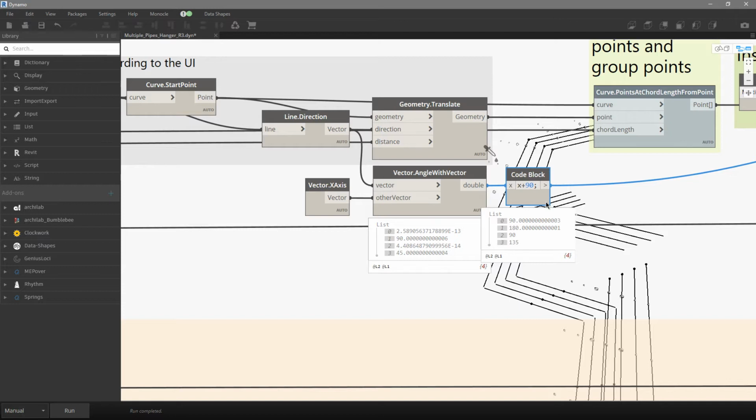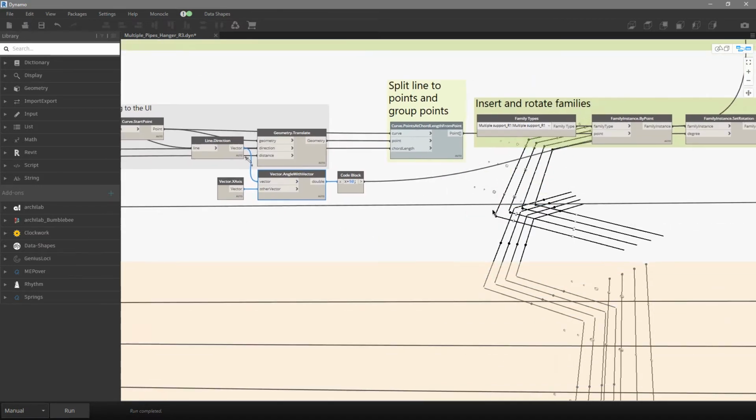I didn't place the family appropriately while I was modeling it. So you need to rotate my family by 90 degrees in order to have alignment with this logic. So this is just my mistake. If you modeled your family differently, you can try to go without those additional 90 degrees. If everything is okay, you don't need this part over here. That is okay.